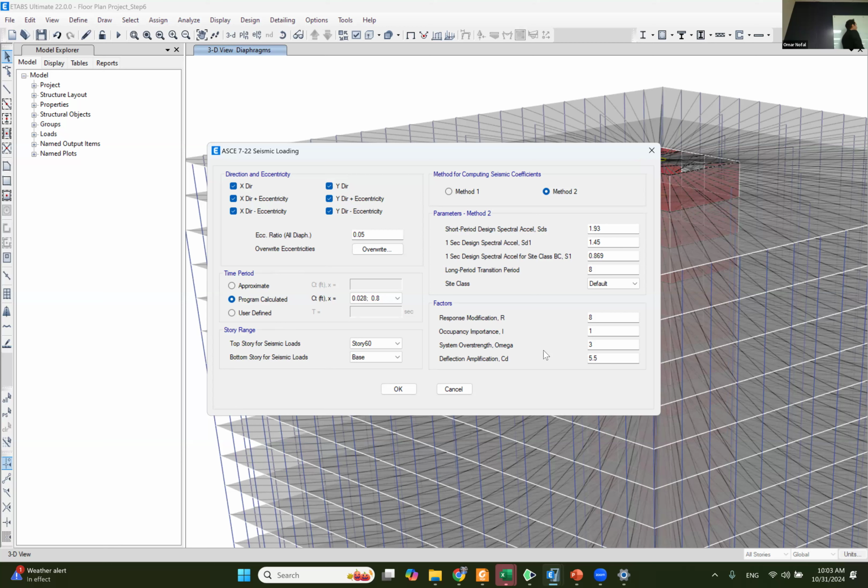But if you have a shear wall here, and a shear wall, let's say, here, the center of inertia of this slab is gonna be also in the middle, something in between these two. But if you only have one of them, this one is gonna be a little bit shifted, right?